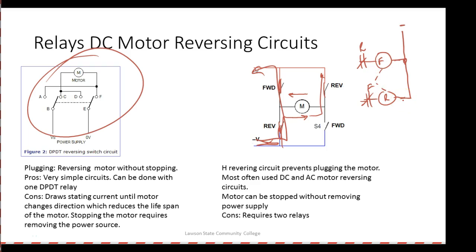This keeps you from really screwing up and mechanically pushing in both of them at the same time. So the best way to do it, and this is not in the PLC, this is out on the relay, right? You understand that? The best way is to use both mechanical and electrical interlocks.